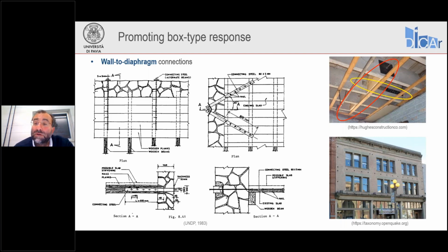In the orthogonal direction, within the red ellipse, we have instead a threaded rod, with a bearing plate against the perpendicular joist, and then you see that parallel to that rod, a blocking system has been introduced, so as to resist the compressive force and avoid bending the joist where we have placed the bearing plate.